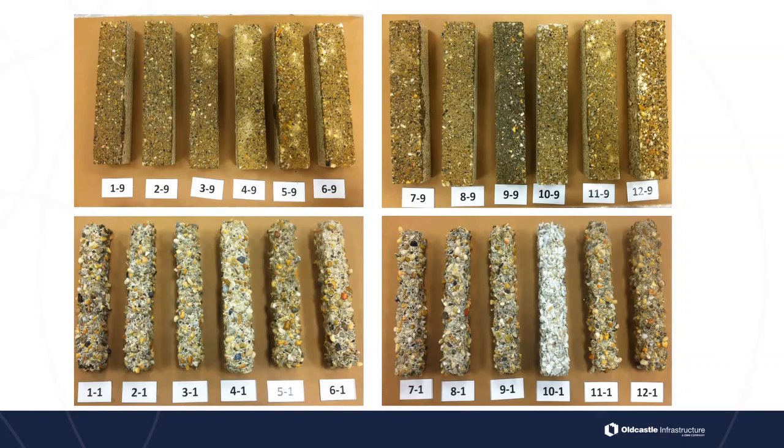And what they found was that a high water-to-cement ratio shows a reduction in performance of the concrete. So you want a lower water-to-cement ratio if possible. And they also showed that supplementary cementitious materials, or pozzolans, show generally improved performance when exposed to these acid levels. So kind of what we would expect to see by the science that we discussed earlier. But they also learned that the acid test could be modified to provide a little bit less gray area in these tests.